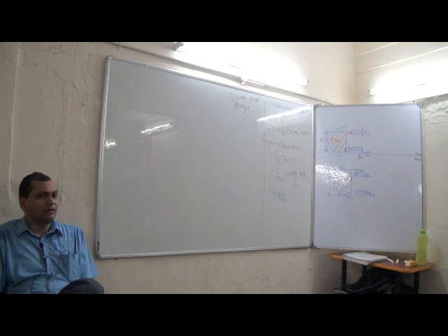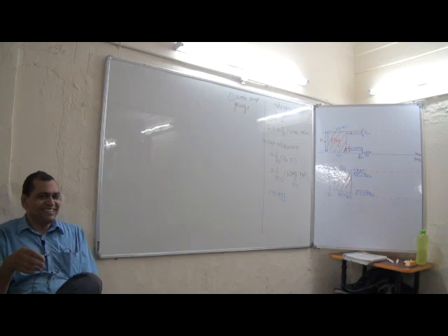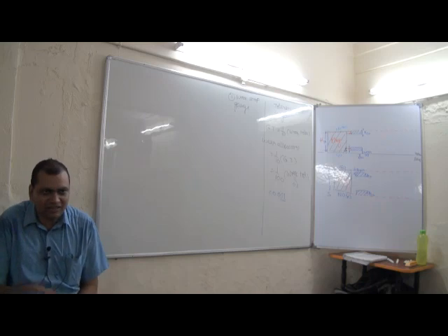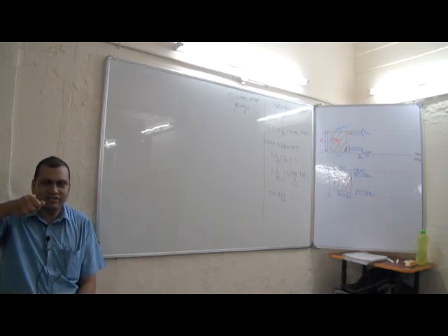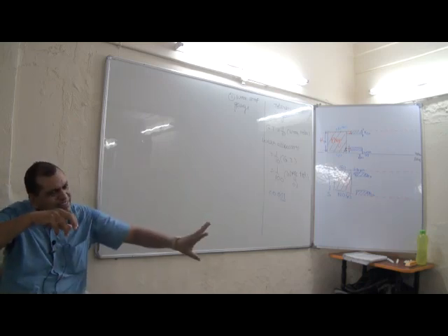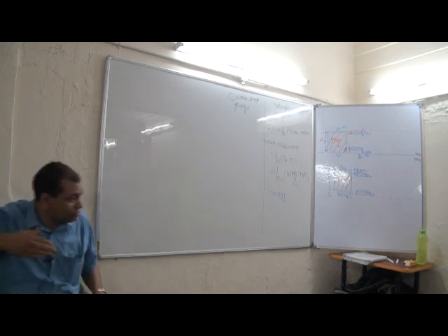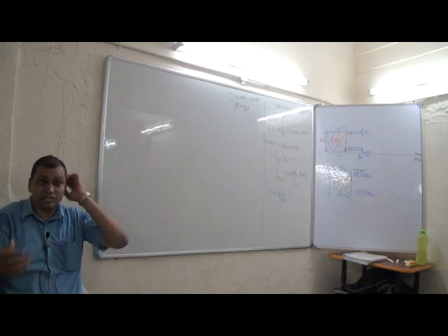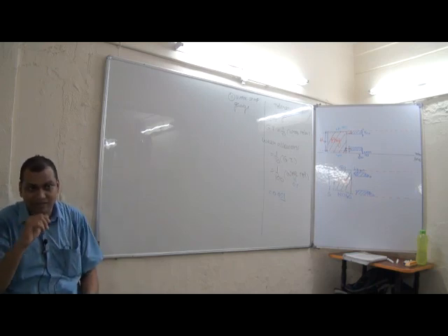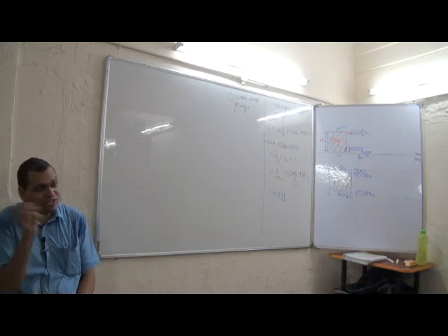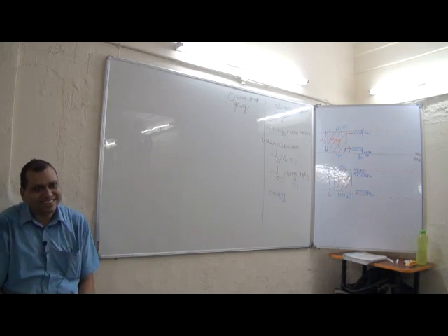So why is there no wear on the no-go gauge? Because it is not moving inside and outside. But there are some holes which are above the tolerance also. When the no-go gauge goes a little bit inside, throw it away. So it is primarily outside only. But the go gauge has to go through and through because it has to check the shape also. That's why there will be wear. On the no-go gauge there will not be wear because it is going only outside, but every time the go gauge is moving, so there will be wear.